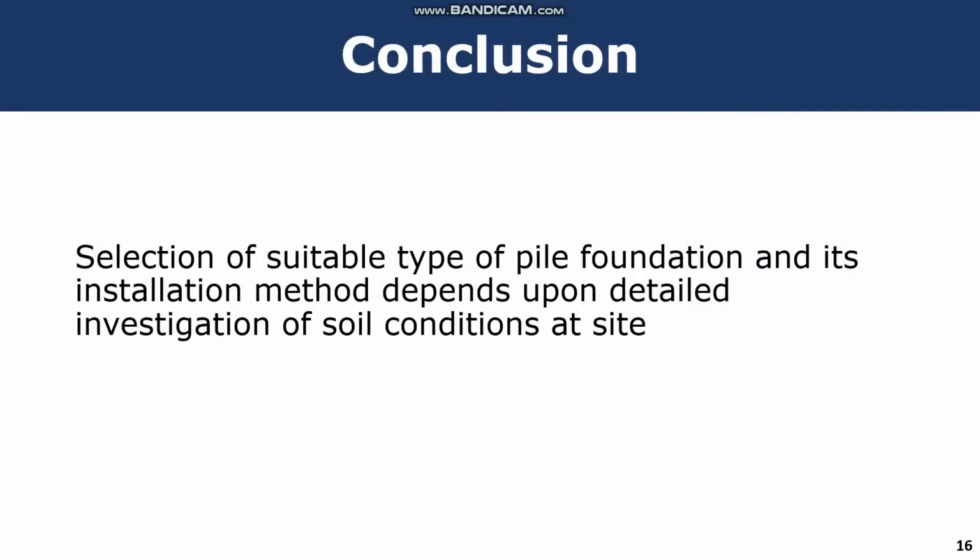So the conclusion is that the type of pile you are utilizing for a foundation and the installation method depend on the investigation of the soil condition. Whether the soil is loose, whether the soil is coarse, whether the soil is cohesive or non-cohesive. On the basis of that, you choose your pile, and you choose which method you will utilize for driving that pile.